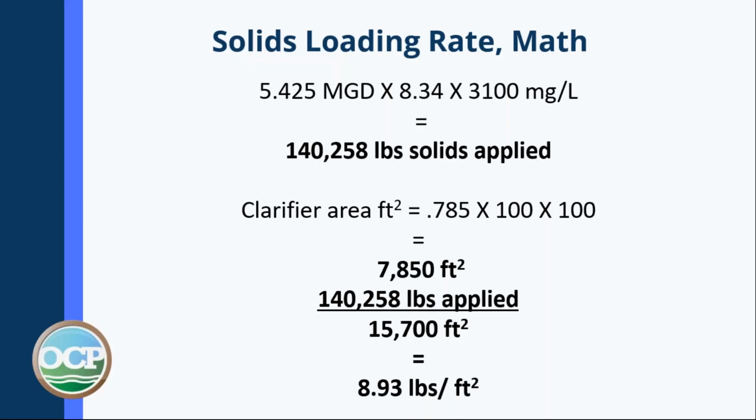So your solids applied, 140,258 pounds of solids, divided by 15,700 square feet of clarifier, gives you a solids loading rate of 8.93 pounds per square foot.